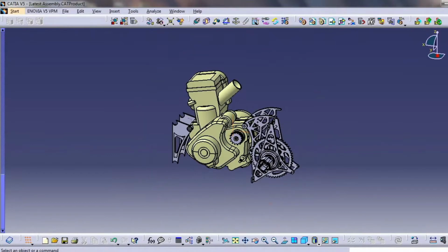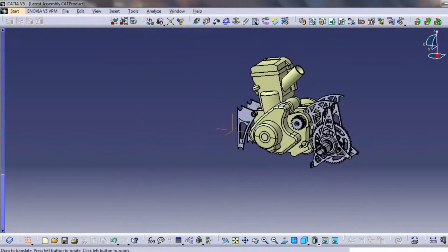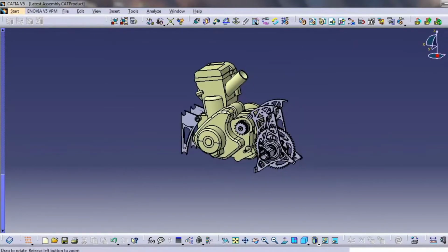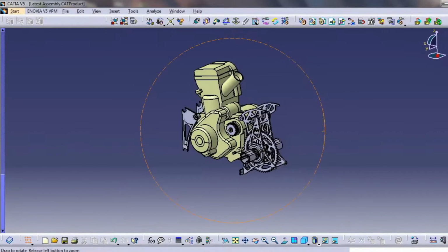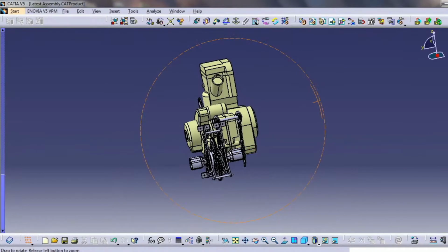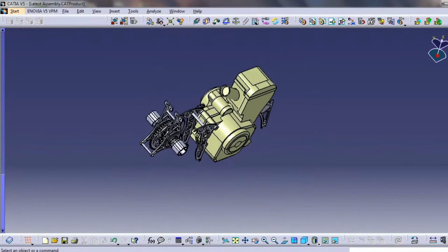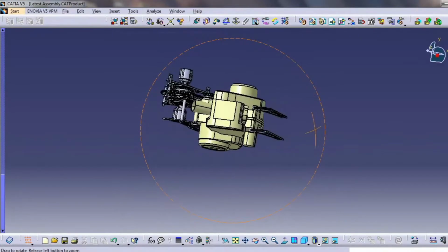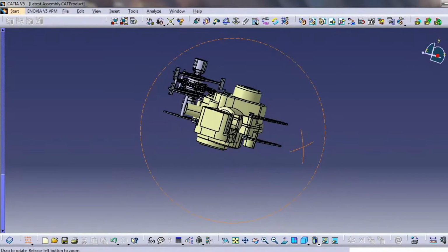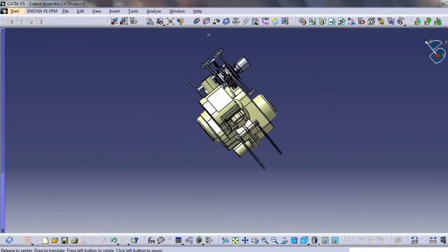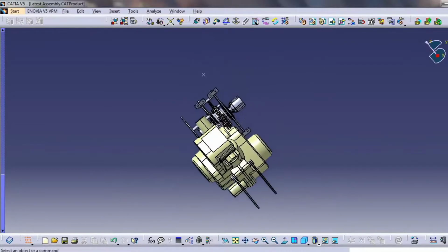Now let's move on to the intake system. As per the rules of the event, we have to use an air restrictor. So for the first 2 years, we used an orifice plate, which is used to reduce the air intake. But it had some drawbacks, such as pressure difference. So to overcome these drawbacks, we use the Venturi plenum assembly. In this assembly, the Venturi does the part where the air is restricted and the plenum is used to recover the pressure losses.